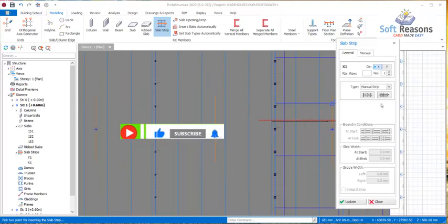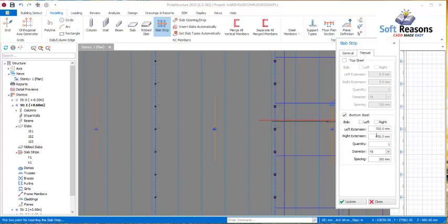You notice you are supposed to use boundary conditions, but when you are using manual slab design in Protastructure, there is no need for boundary conditions. So you can see all of the boundary conditions options right here are inactive. So get back right there, make sure that you feed in everything necessary correctly in these particular provisions, and you proceed.